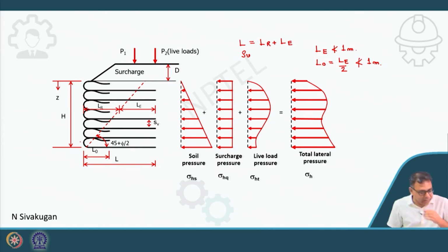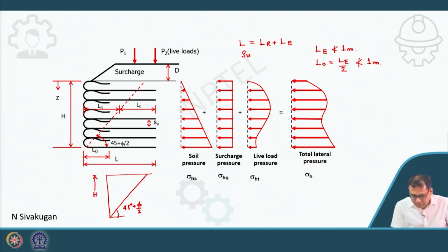Another thing, this failure surface can not always be triangular. It is planar, this type of failure surface. Suppose this is the failure surface, this type of failure surface that we have discussed, that is shown here, that is 45 degree plus phi by 2. If this is the height h of the wall, then this is applicable for extensible reinforcement.